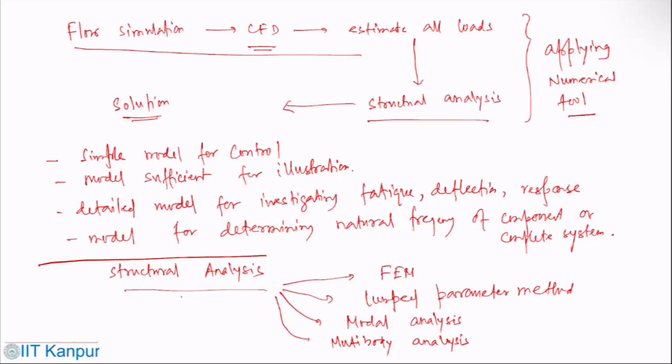For example, a wind turbine includes tapered or twisted beams, various other tapered parts, couplings, generator, gears. The bodies may move in a variety of ways with respect to each other. Bodies could be rigid or flexible. Bodies are joined together by links, which may incorporate certain constraints. So the multi-body method involves the creation of dynamical equations involving the various bodies and their constraints.